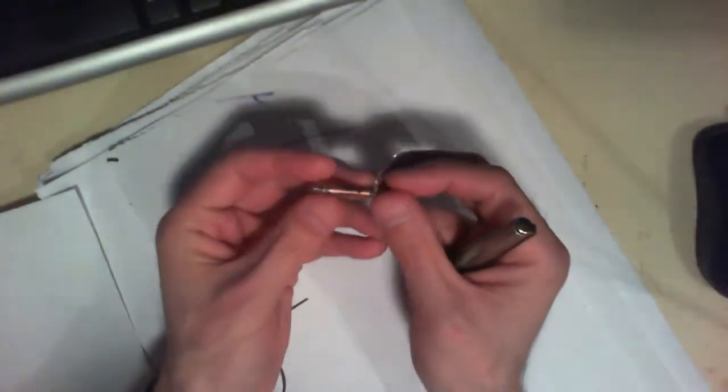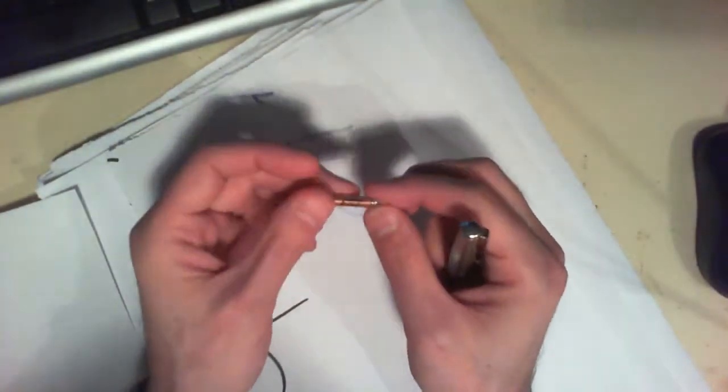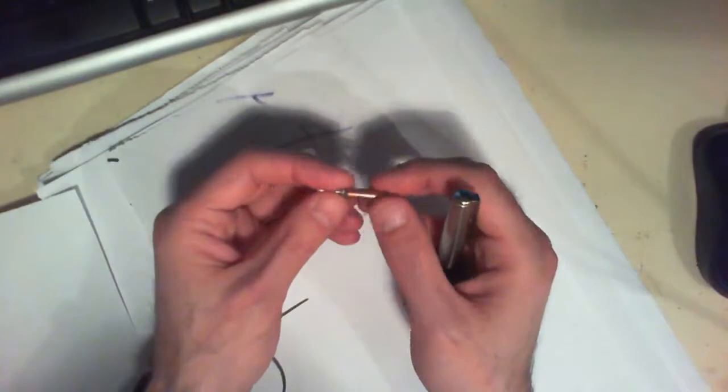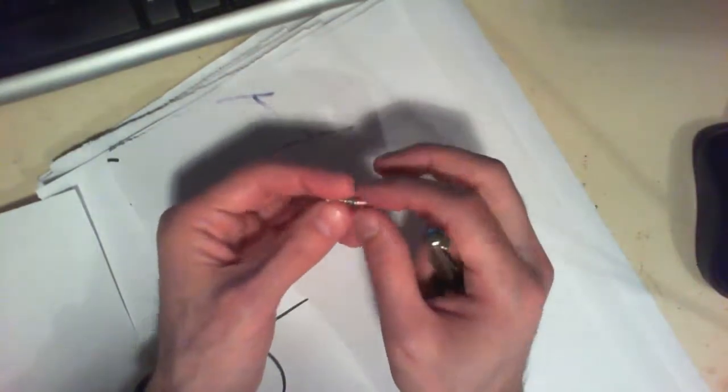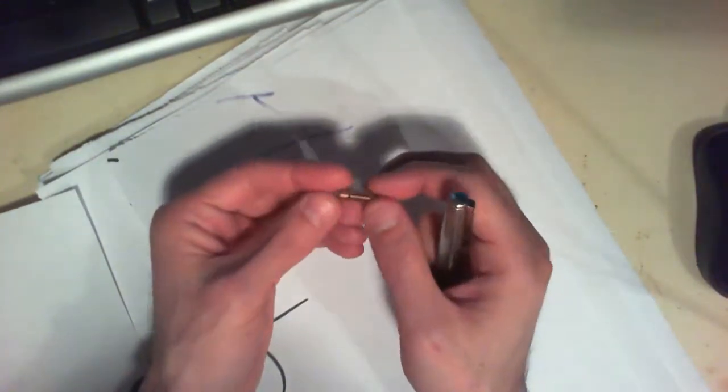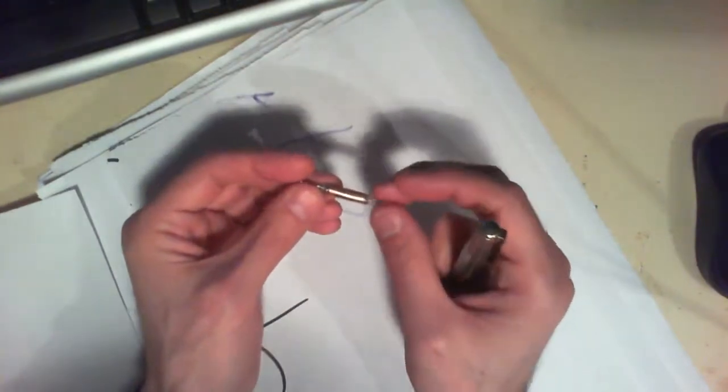So in this video I want to show you how you can use an oscilloscope and a signal generator in order to measure the inductance of an inductor. For example, let's say that you have this inductor over here, you have pulled it out of some circuit, and you don't know the value of the inductance, and so you want to measure it.